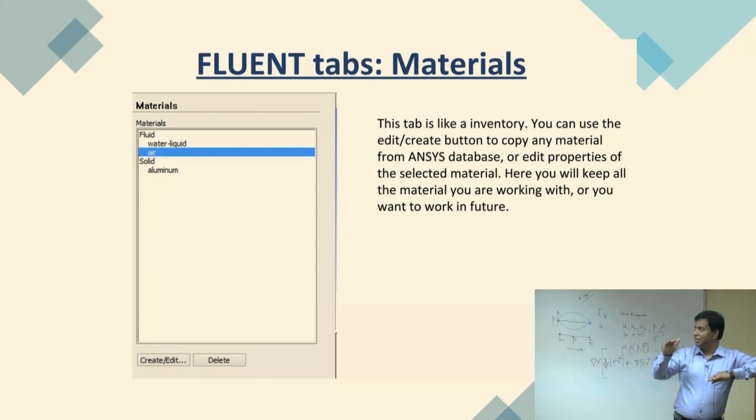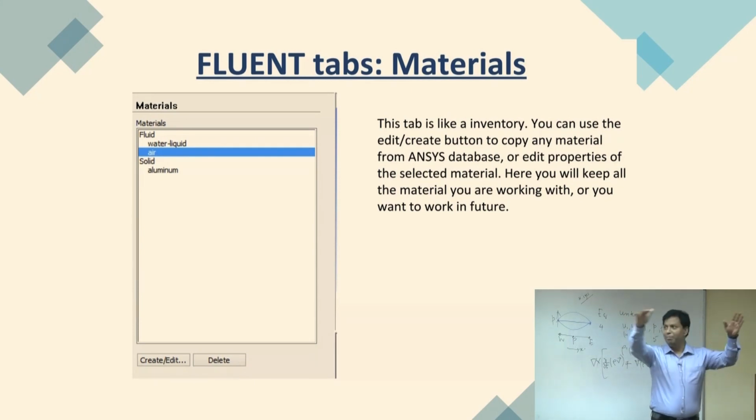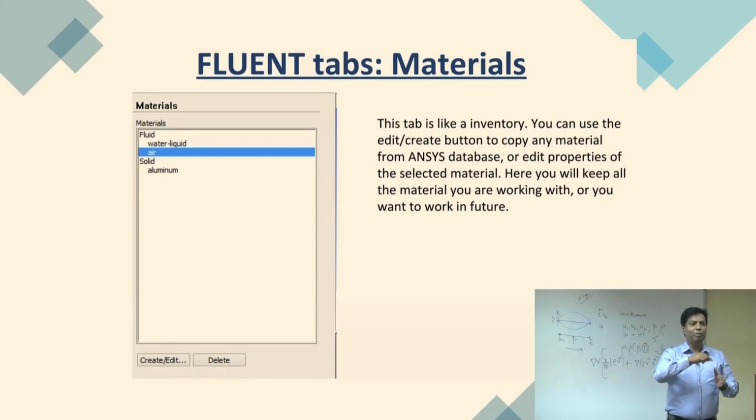Scientists care about parameters like the Reynolds number, Prandtl number, Rayleigh number. Those are generalized: all the dimensions and parameters go into that. So it doesn't matter if it is a very big room or a small room. If you set the parameter, that represents everything. Okay, so this is the difference between the engineer and the scientist.